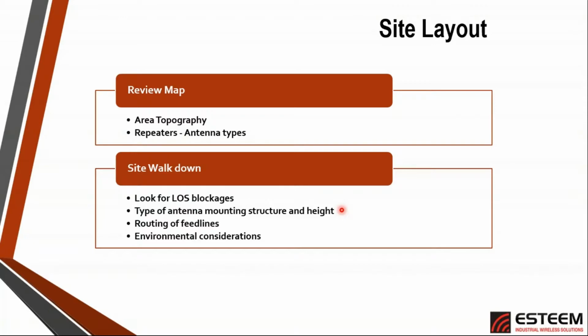That's the main purpose behind it. The next thing to consider is the routing of the cable. Now, for the pole mount type of installations that we have on our Horizon series radios, you have quite a bit of flexibility with the routing, because you can move the Ethernet cable almost up to 300 feet on those with very minimal amount of problem.